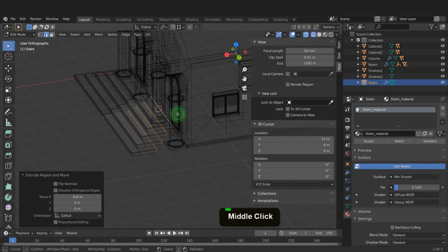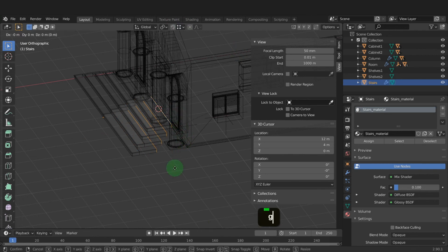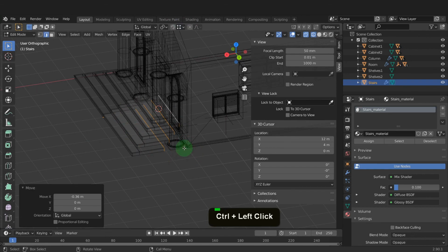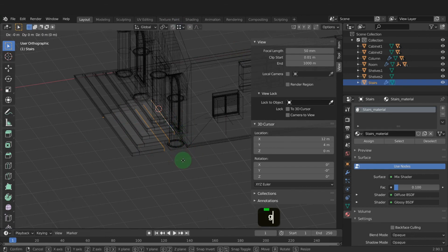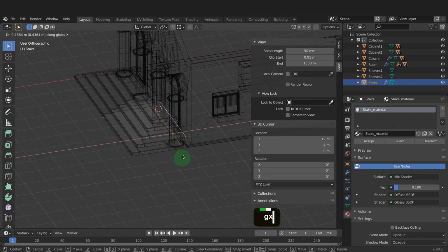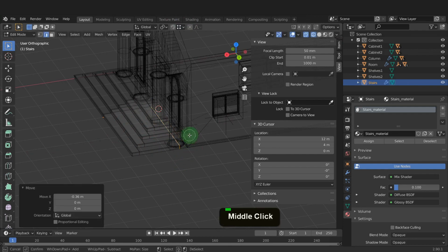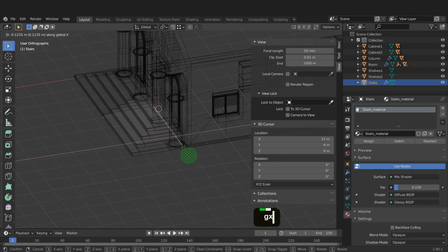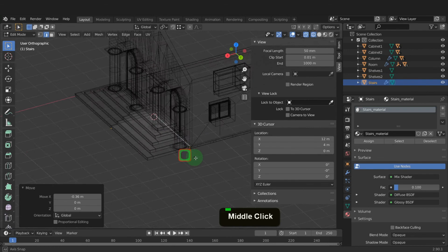Press C and deselect the top edges. Now snap the next active object into the wall. Repeat that down along and snap each step into the wall and finish off this area. The active part setting can be really useful in situations like this.